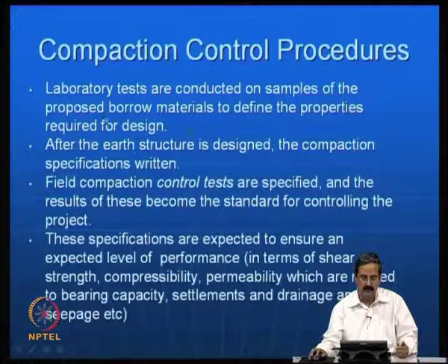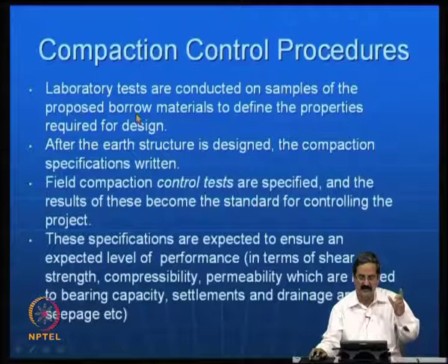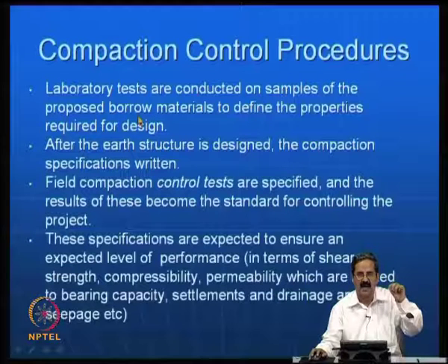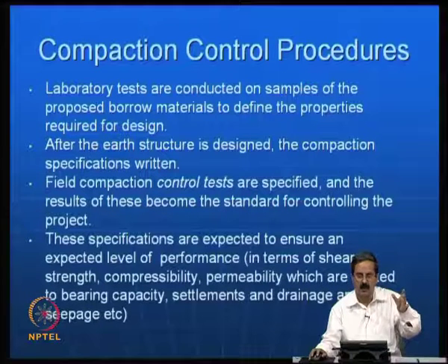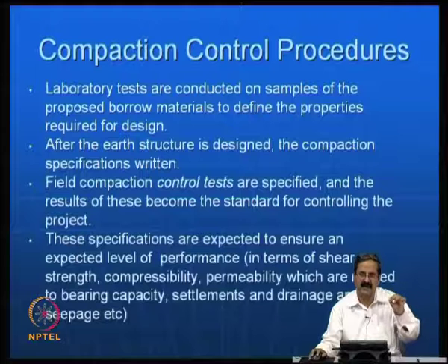So you have to specify some properties for that material. We call that particular soil layer above the expansive soil a cohesive non swelling layer. It is a cohesive material, but it does not swell. What it means is that it has defined properties like cohesion and friction angle, it does not swell and all that, whereas the base soil is swelling.